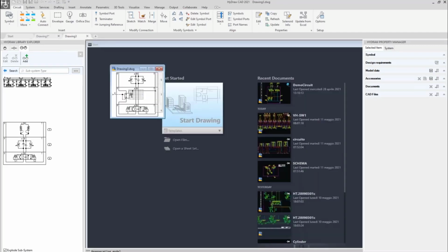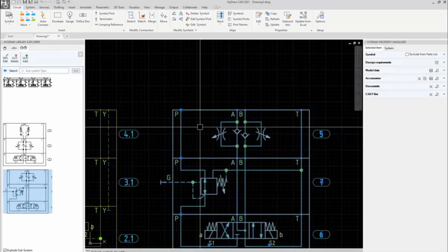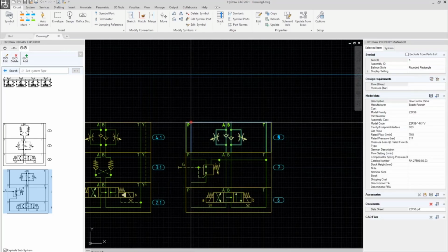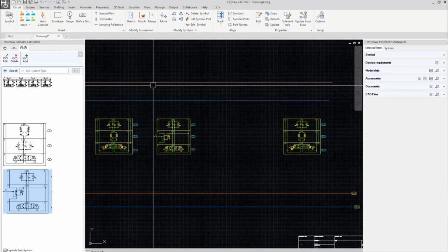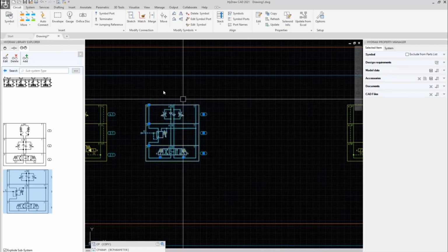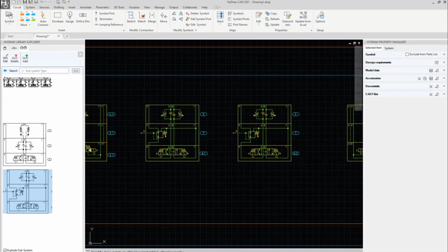We have also a very good build symbol mode I showed during my last webinar last month. And this is working very, very nice too. And you are very fast when making new symbols. Let's say that these items I copy. So using the AutoCAD command copy, I position another element here. But in this case, I don't need the reducing valve. So I need to break my stack. So delete, and I make a new stack here.